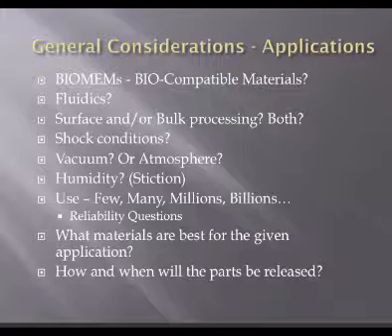So when you put the next part on top of that, there's a space, right? You can't just layer the same material on top of each other because then they'll all stick together. Nothing will move. So you got to provide some space. Now you got to get rid of that sacrificial material, that scaffolding that created that space. So how are you going to release the part, right?